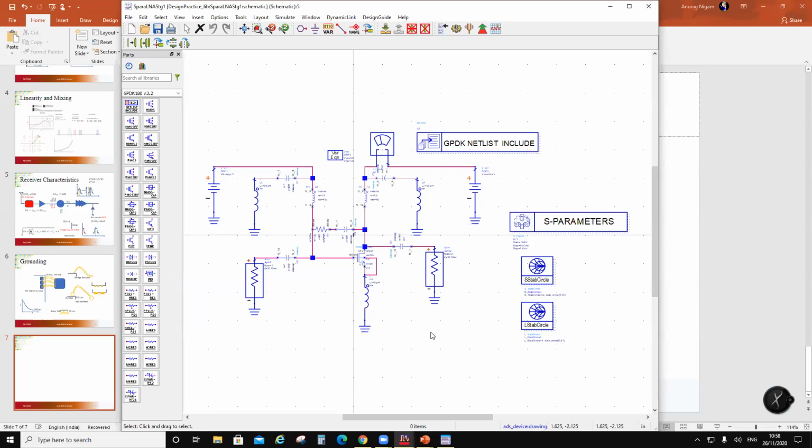stick to the theory. Don't stick to the boss. This I tell you in SAC also when I go there. Stick to the theory, not to the boss. I went to analyze a Gilbert cell mixer for down conversion in SAC. And the top guy told this junior engineer, I need a 30 dB isolation between RF and LO.